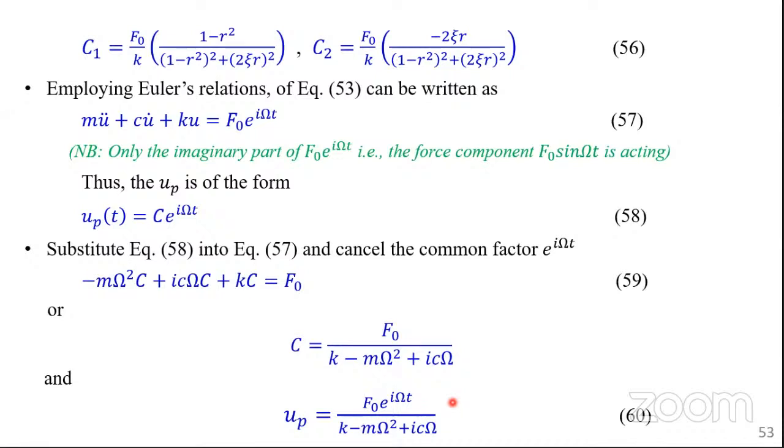It assumes that you already know the different types of damping that will occur. There is external damping, just because of the fluid in the air; the structure is vibrating in air, not in a vacuum. So the assumption you make is based on your understanding from the theoretical point of view, but again, you are not alone because you are guided by the code, from the experience of other people, which are brought together to constitute the design code. I hope I'm bringing it out. I know you are wondering, if I'm told to design, how do I know whether I will consider damping or not? Of course, you design using code.